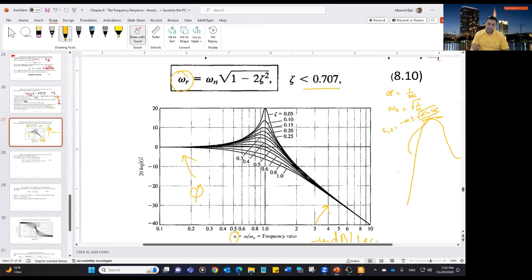And that used to represent the natural resonant frequency, negative alpha plus or minus j omega n, where omega n is the square root of omega naught squared minus alpha squared, if omega naught is greater than alpha, or alpha is less than omega naught. So as you can see, this was omega n basically in circuit analysis.